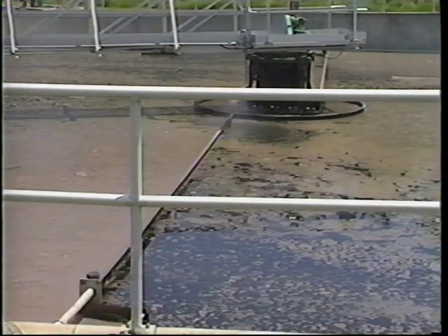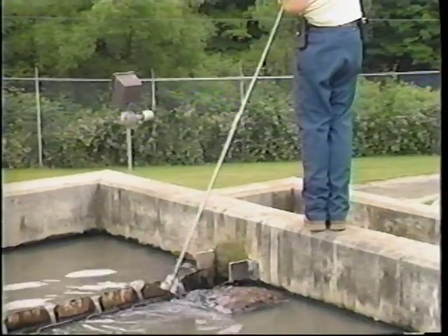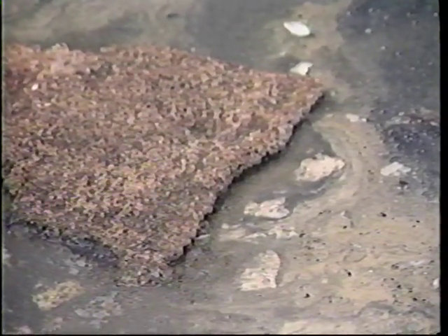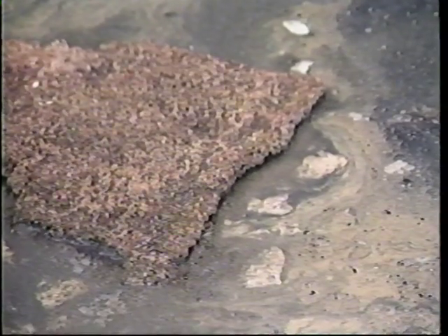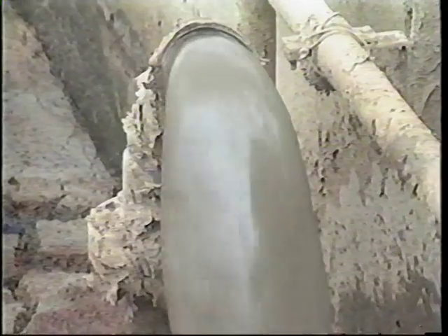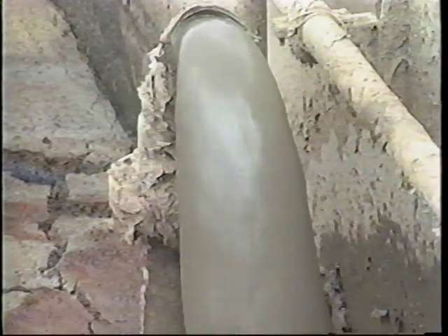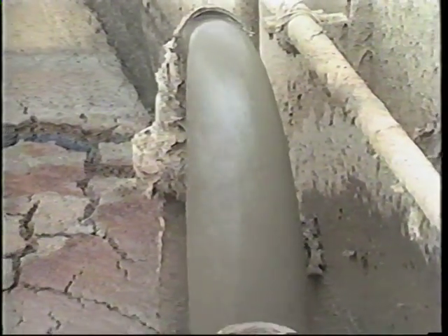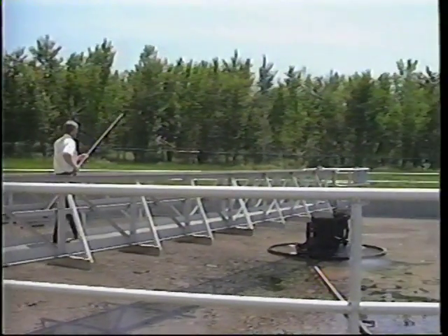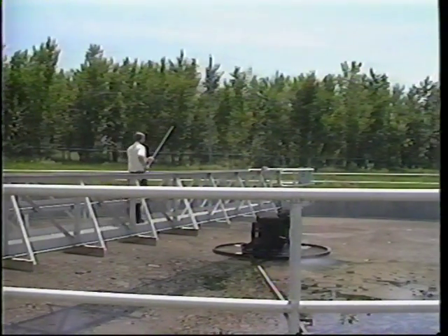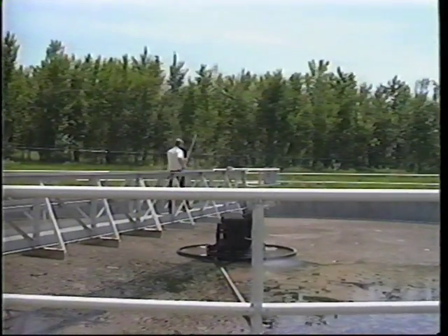If clumps of floating biosolids are found on the surface of either primary or secondary clarifiers, it indicates that the biosolids are remaining in the clarifier too long. Biosolids removal rates should be checked and increased if necessary in order to prevent the biosolids from rising. The collection mechanism should be checked for malfunctions as well. In some cases, the solids in the hopper tend to hang up, and it may be necessary for the operator to use a long pole or squeegee to scrape down the walls of the hopper. Care should be taken when scraping solids from the walls of a hopper to prevent excessive turbulence.